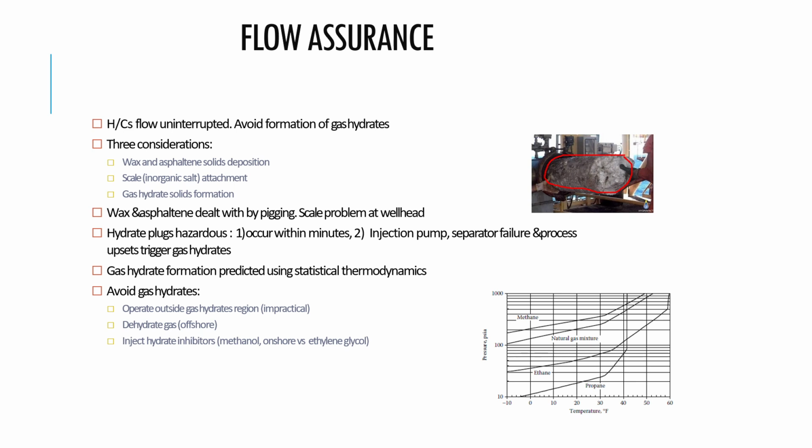And second, certain conditions or circumstances might contribute to the formation of hydrate. For example, if you have an upset in the pressure or in the operation, such as a failure in the separator or in certain pumps or compressors, this might also provide a good chance for the hydrate to start forming. We will talk about gas hydrate in more detail in the next few chapters, but normally gas hydrate formation is predicted using what we call statistical thermodynamics.